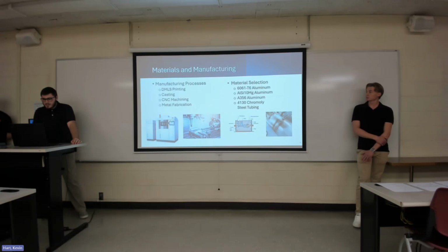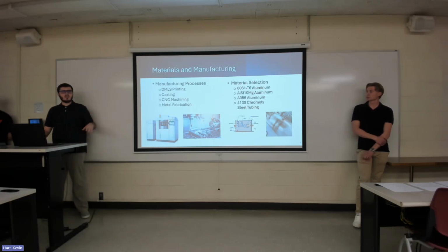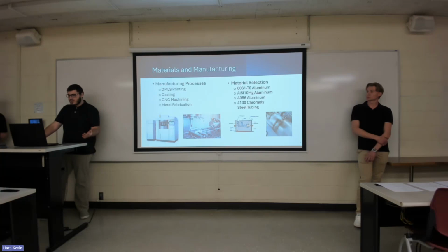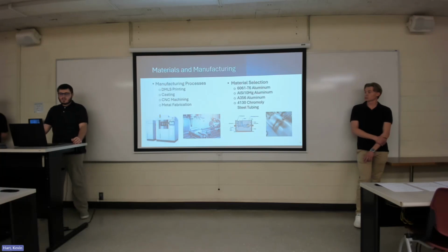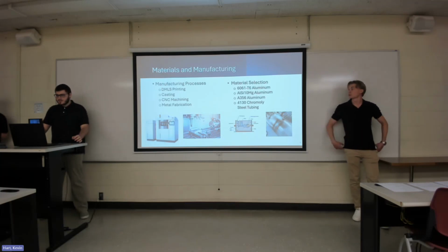And typically after the design is made, there are supports and the surface finish might not be up to spec with certain interfaces such as a bearing going into the knuckle. So there are certain treatments that need to be done after it is printed. Typically, this utilizes aluminum silicon 10mg for a material to print out of. This is a really high quality material to print. It has great flow properties and works great for printing with DMLS.